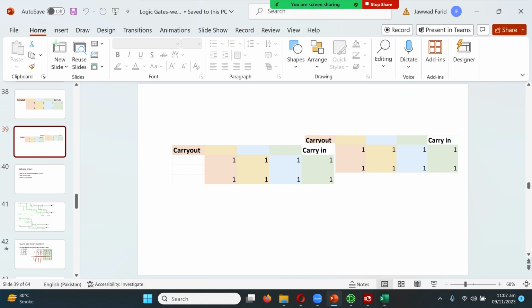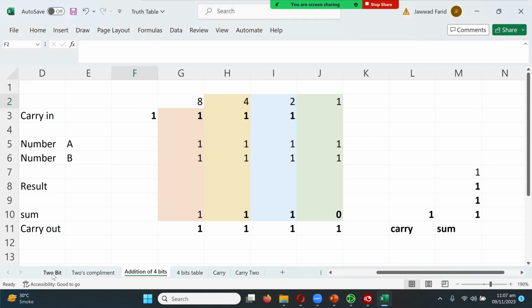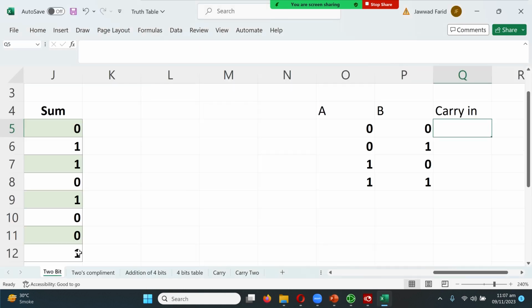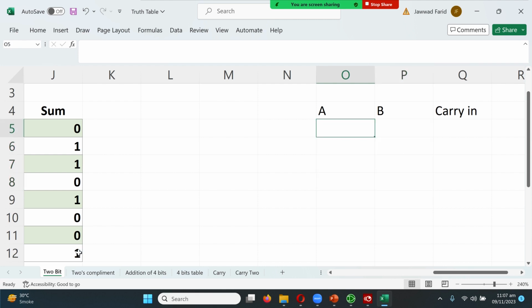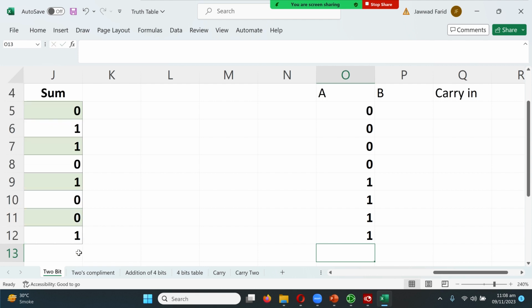So now when we look at the truth table that we made here with 2 bits, when we add carry in in this truth table, we now have more choices. So we will not have 4, if we have 3 inputs, then 0 0 0 is one, and then we get 4 more, including 1 1 1, and that makes 8.